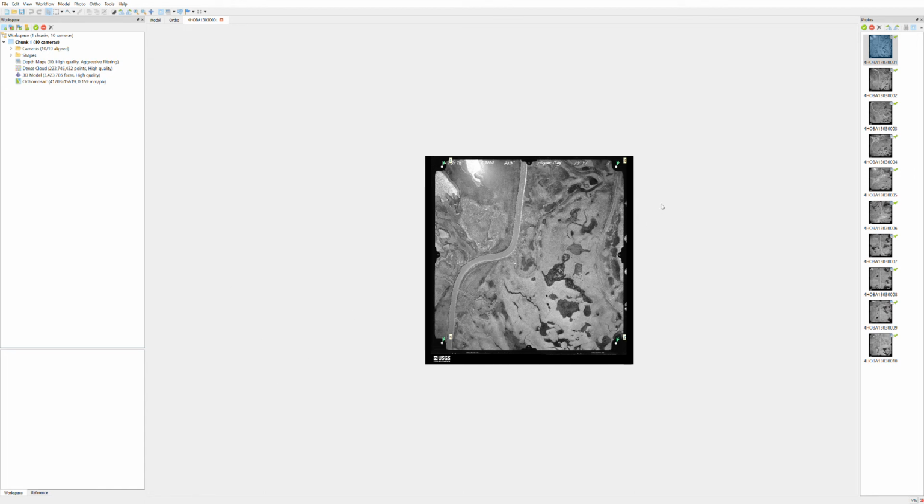And that's just going to help the program in the long run really put these images together and get a good lens distortion. Because when these are scanned, they're physically printed out images and then scanned on a scanner, and they kind of jumble around as they scan, and they did their best to keep them centered and straight, but the fact is that they move around a little bit, and so the camera center moves and it starts to cause issues in the lens correction and other things down the road. So this resolves that as best we can, and we'll press OK. We are happy with our coordinates, and let's see.